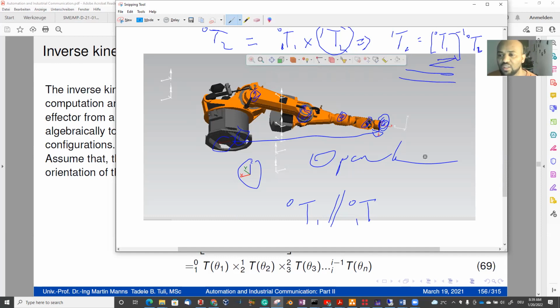This is so inverted. Now, for such inverse kinematics, we have to know how to do the inverse of the matrix. In other words, the matrix has to be invertible. That's why we wanted to make the matrix full rank. Last time we added the last row with 0, 0, 0, 1 in order to make the matrix full rank, so that we could invert it. So we could easily calculate the inverse kinematics.